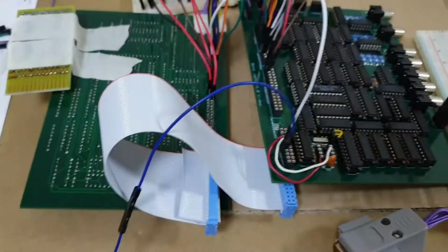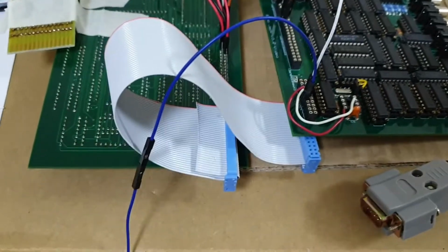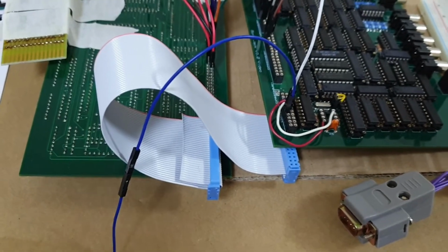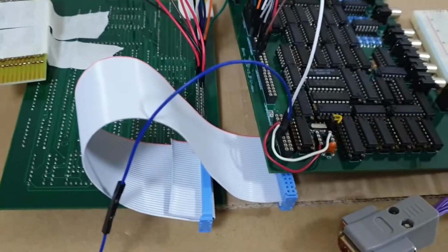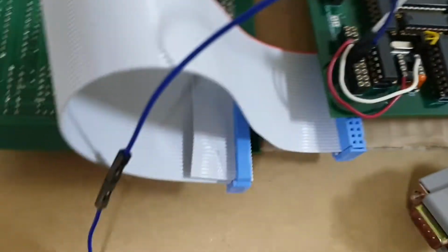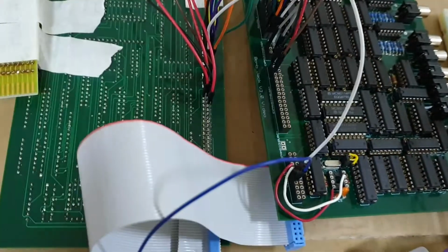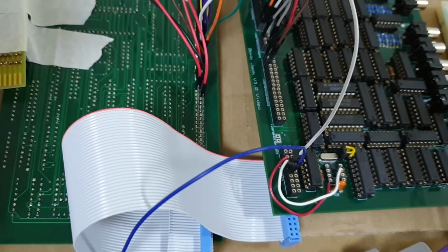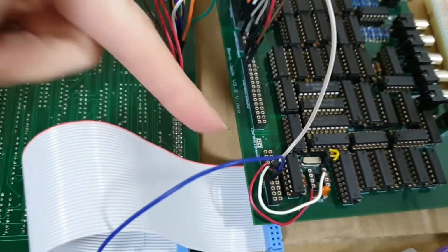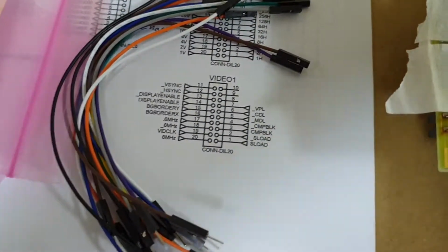So, slight progress. I've removed all of these wires pretty much and replaced them with this, actually a relatively long ribbon cable. It's this one here. I'm going to put a little tick on it later on, indicating the position of the plugs that I'm using. By convention there's this little red line along one edge here, so I'm using this side to sync up with this header here. This is the video 1 header. You can see all of the signals that go into this.